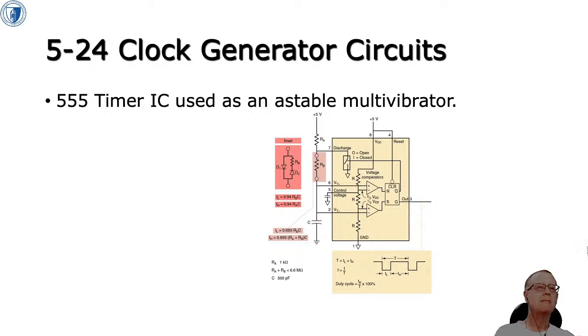So the top yellow box is the insides of a 555. On the output, you can see we've got an SR flip-flop. On the inputs to the SR flip-flop, we've got two voltage comparators. Does anybody know what a voltage comparator is?